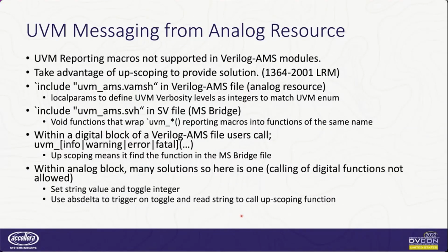We're going to use the upscoping capability that's in Verilog and SystemVerilog since the 1364-2001 LRM. And that Verilog syntax is supported in Verilog-AMS. And so we can use this upscoping within our Verilog-AMS to access the methods in our bridge by using the upscope capability.